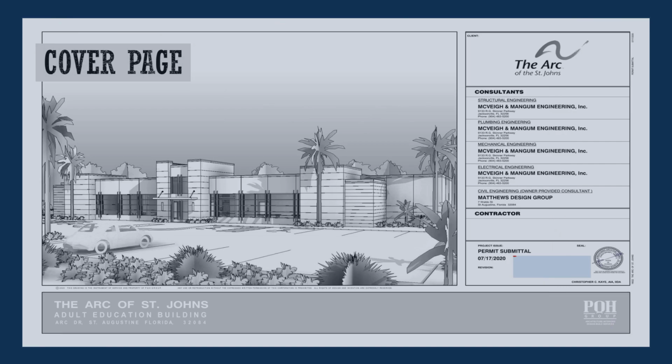When you first examine a set of prints, the title and cover page will give you the preliminary information you need to make sense of the rest of the plans. The page contains the plan index and reference list of all the drawings contained in the set. Any changes made to the plans are listed in a revision block that's typically located in the title block. Read these items first to understand the scope of the building and any relevant information about the architect.